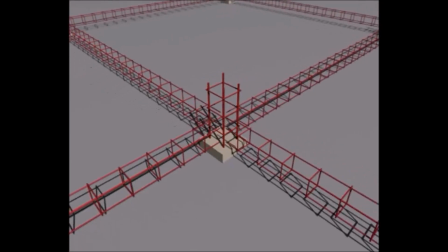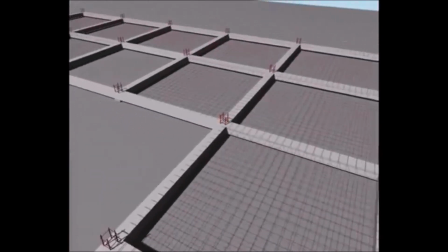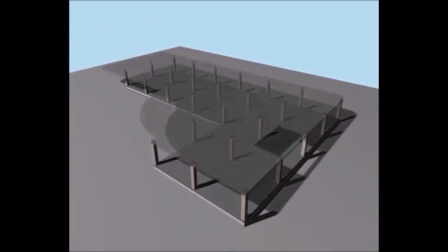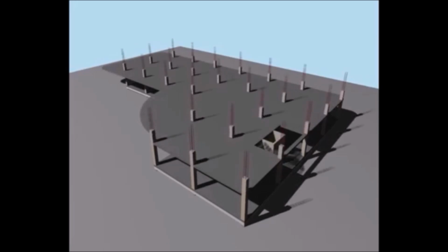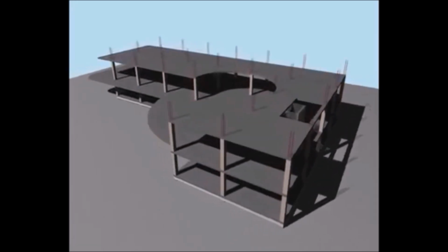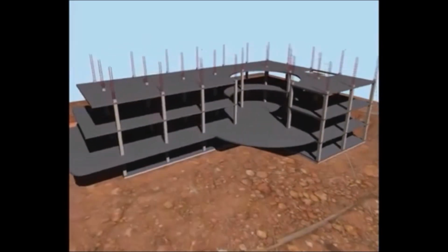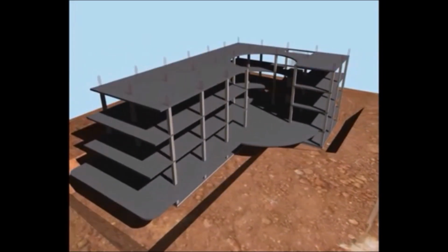In structural engineering, composite construction exists when two different materials are bound together so strongly that they act together as a single unit from a structural point of view. When this occurs, it is called composite action. One common example involves steel beams supporting concrete floor slabs.